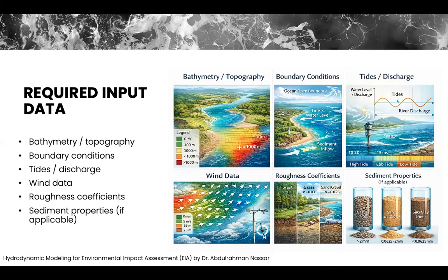Boundary condition: this is the boundary that's surrounding our project area. We're doing the model in a specific water area, and outside the model, this is a boundary. So we should have the data of the boundary, which is the boundary condition, which might be tide, ocean, wind, sea level, or whatever the condition outside, because this is to control the boundary of our model area.